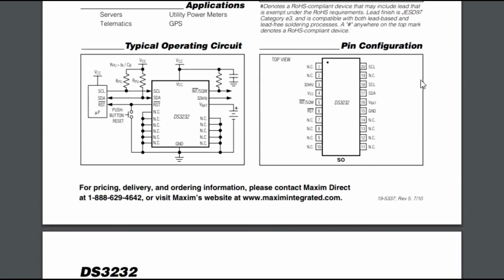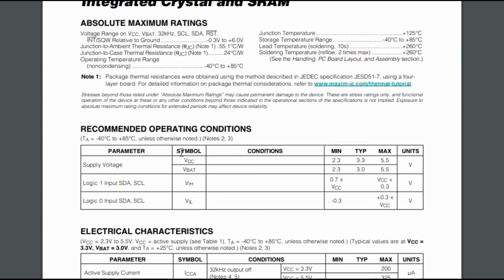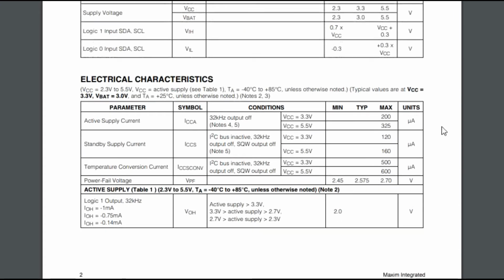Its pin configuration is this one. It has 20 pins. This is the operating circuit. These are certain parameters of it. Supply voltage VCC means it will work from 2.3 volt to 5.5 volt max. Its electrical characteristics are shown below.